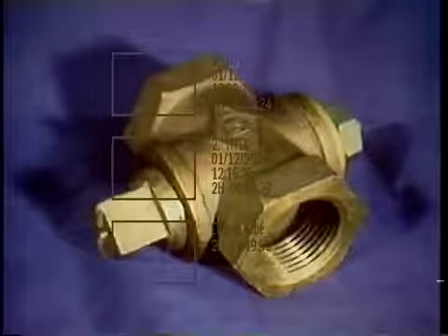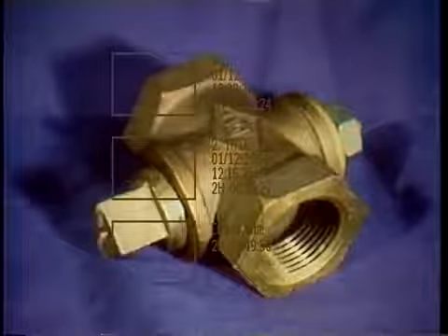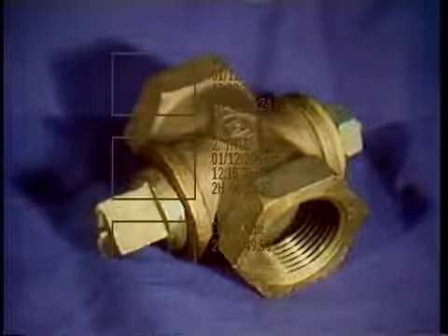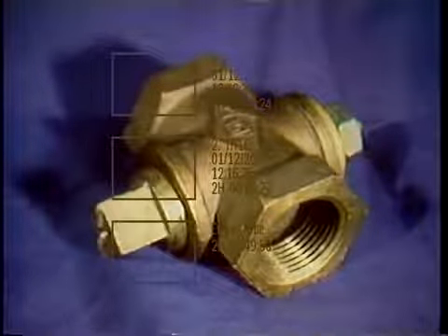The plug valve is very adaptable to systems carrying slurry. Slurry is a fluid often containing large particles. Often the valve will indicate which way the flow is going. For instance, on duplex strainers, the handle will point to the strainer with the flow through it.